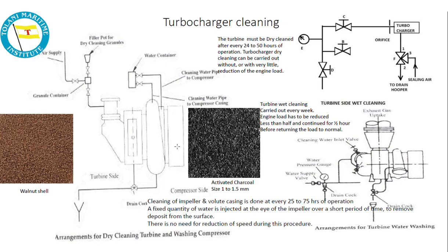Now, if turbine side cleaning is not carried out, then fouling may lead to back pressure and surging, resulting in breakage of turbine blades. So see the importance of this cleaning. If blower side cleaning is not carried out properly, then the supply of air to the engine will be reduced. So that is the reason why we are doing this cleaning.